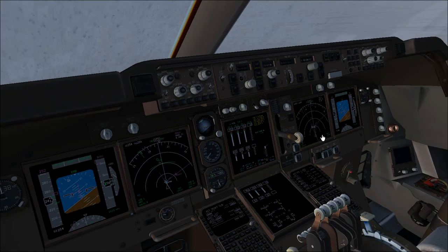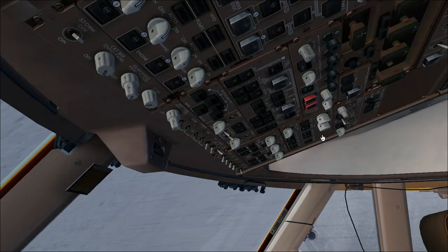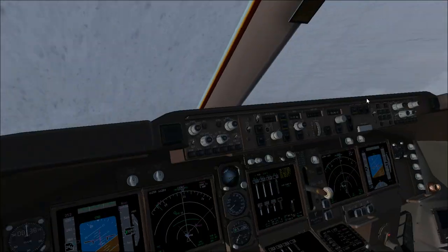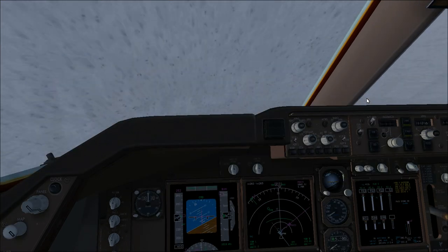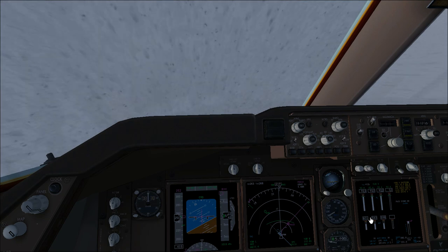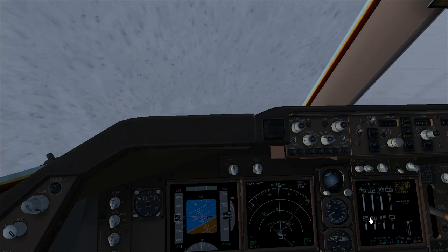The fire is off. We check out the bottle. The bottle should be discharged. As you can see, the bottle is discharged. This means the aircraft has now cleared the bottle, and we have to check the message shows not checked, so no need to release the other bottle.